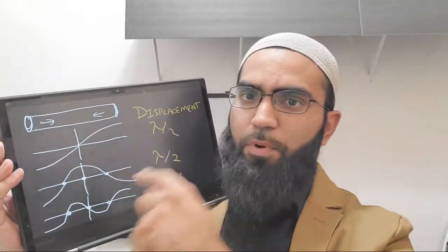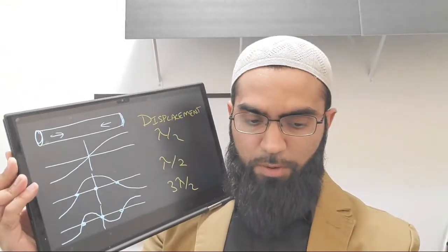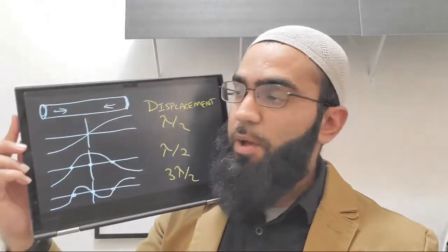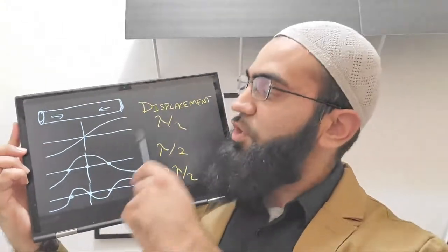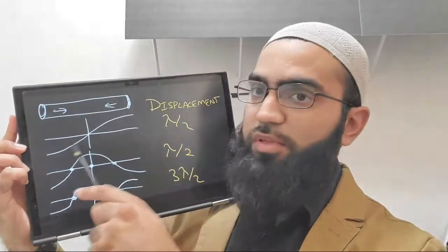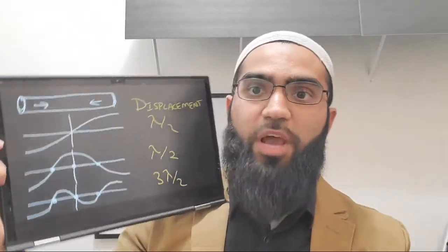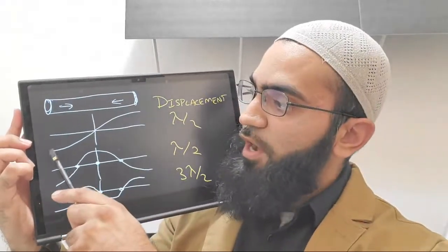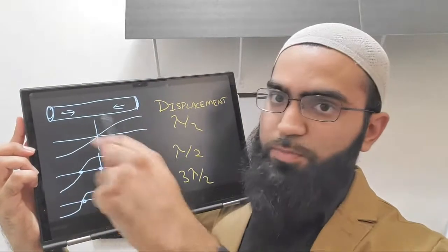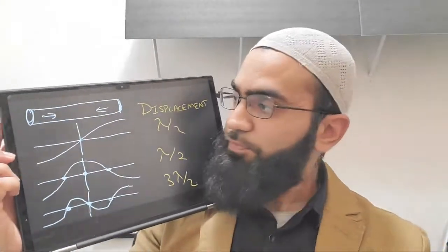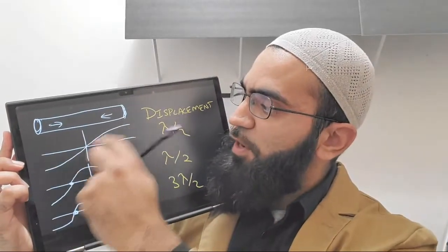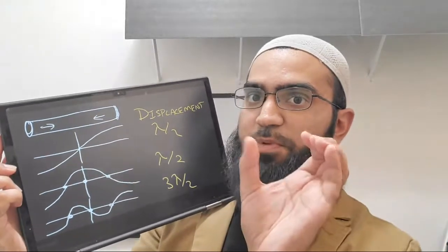So the permissible number of modes is infinite, but the lower order modes, which are going to be excited with the most strength, start with the half wavelength. And the half wavelength is the first mode shape, as we call it, that supports maximum displacement. All these plots are displacement. It supports maximum displacement on the edges. Now we see negative displacement here and positive displacement on this side. This just means it's expanding.